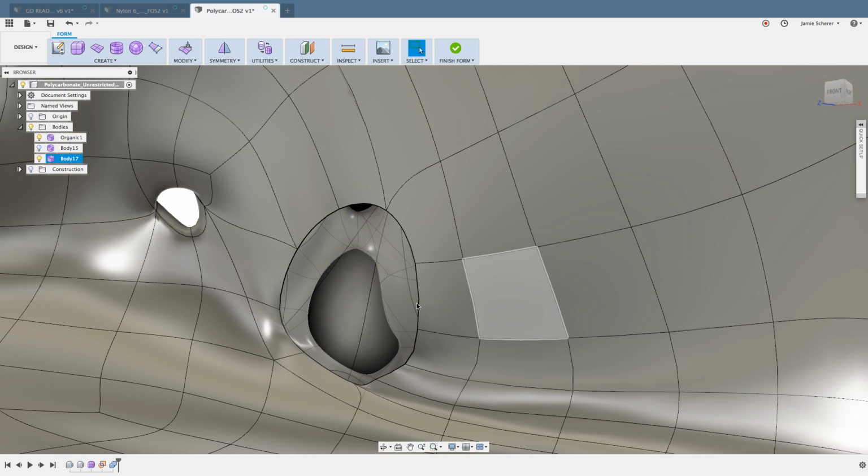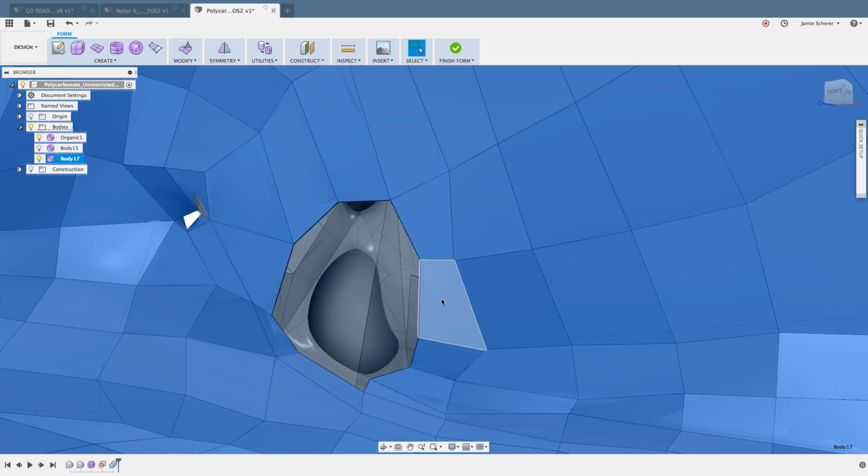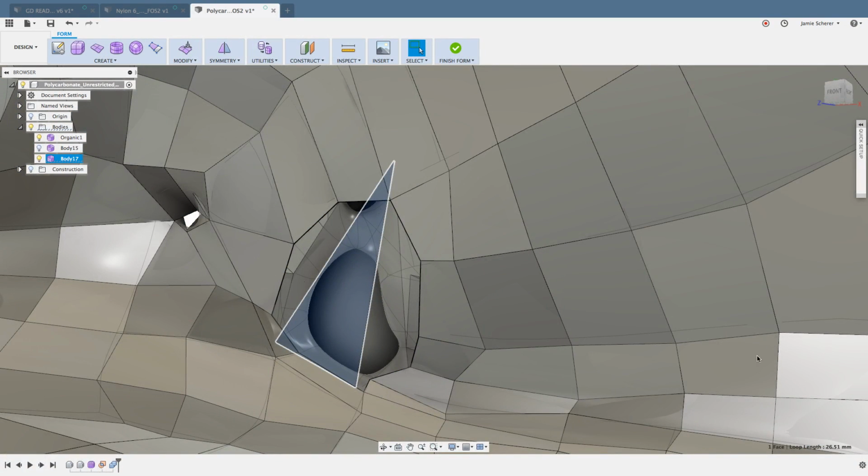So the first thing that I like to do when I'm looking to fill in a hole and match the topology with four-sided faces as best I can, is go into box mode. Box mode always makes it easier to visualize and see what we're working with here. The next thing that I'll do is line up and look at how many faces I have, and what's the best breakdown for how I might bridge or manually build back in faces to rebuild this.